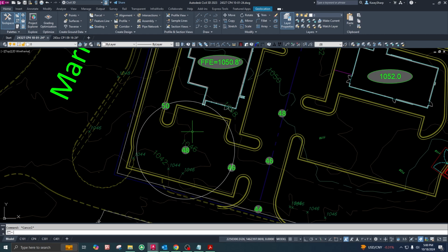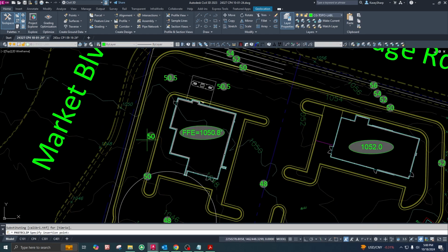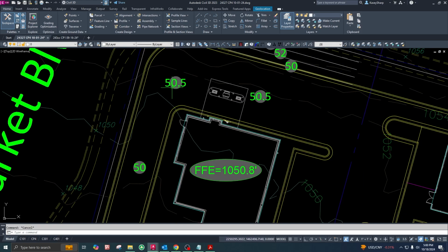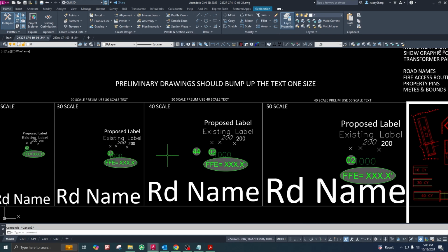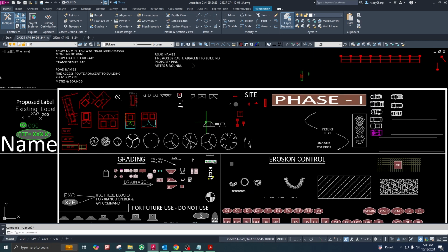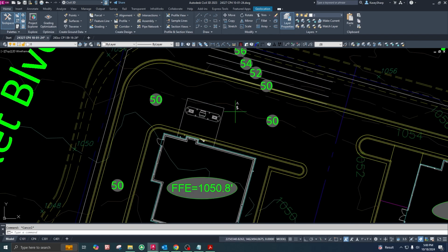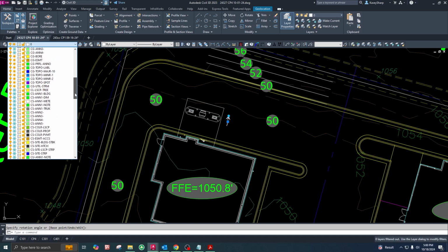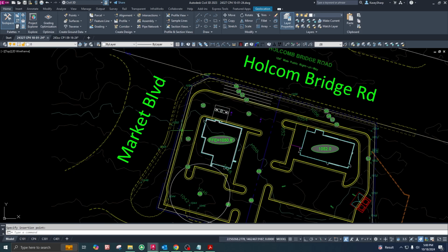Okay, go up 2 feet over 40 feet, give us our 5%. All right, and then we'd have 50s essentially run all the way around the edge. 50, 50. I'm going to go ahead and grab a slope arrow really quick. Let's see here, slope arrow. Okay, everything's going to be sloping away from the building.